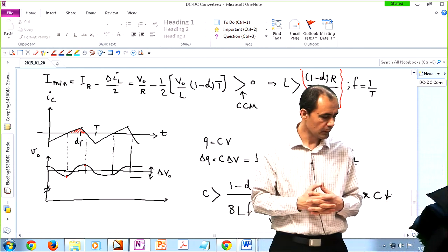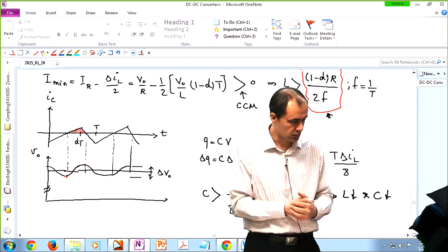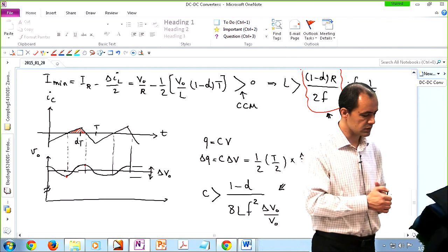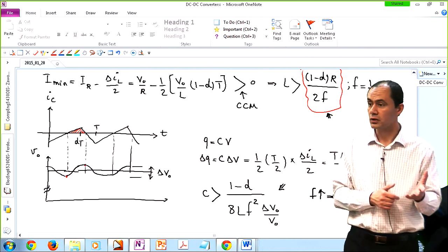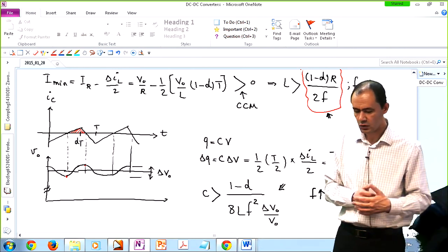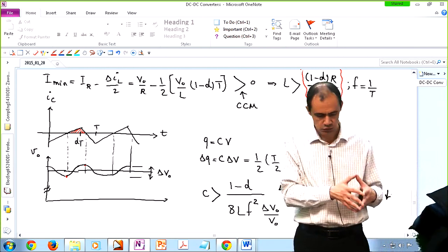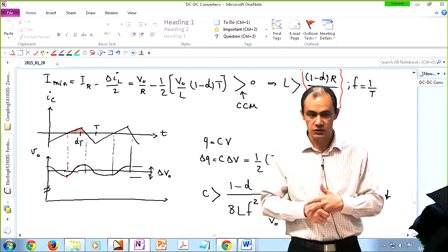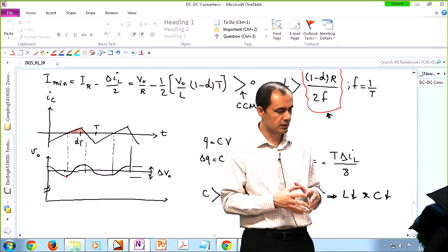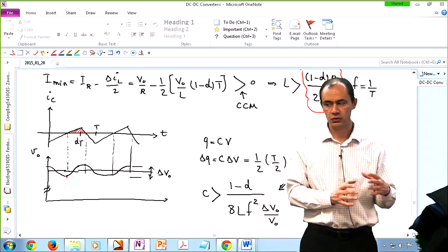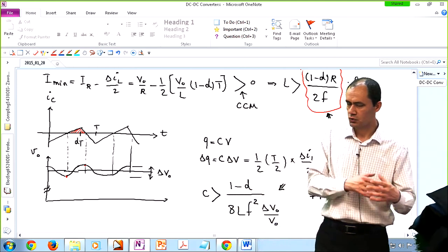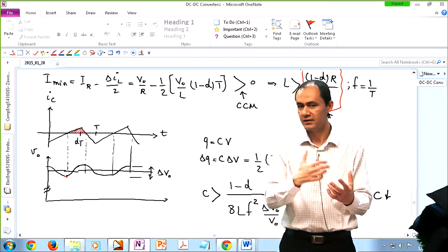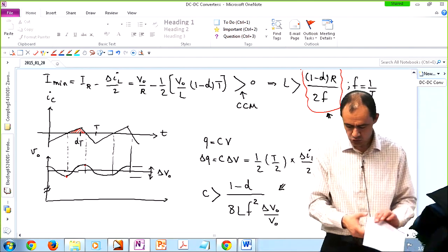And there's a mechanism which is called the switching losses. We are going to see that later. If I keep increasing the switching frequency, the switching losses are also going to increase. That means you're losing a lot of energy in your switches, which has two disadvantages. One, obviously, your efficiency goes down. The other one is, in order to get the heat out, you have to use a bigger heat sink. So you're trying to make your inductor and capacitor smaller, at the same time you're making your heat sink larger, or you have to add a cooling fan to your converter. So there's a compromise involved.